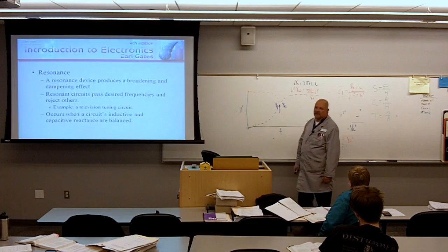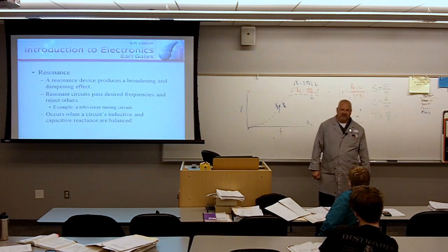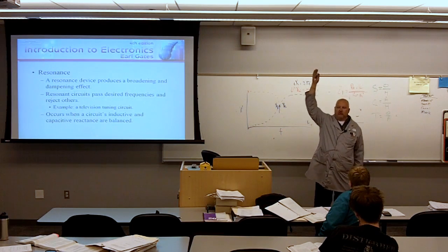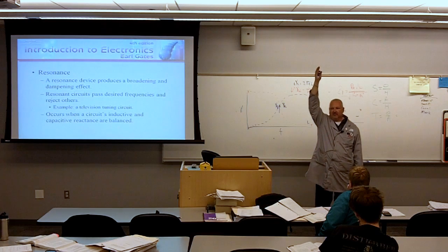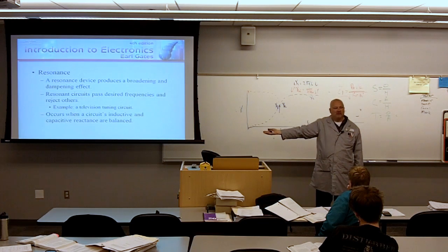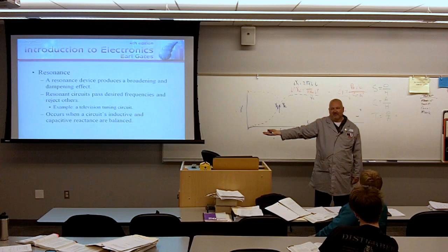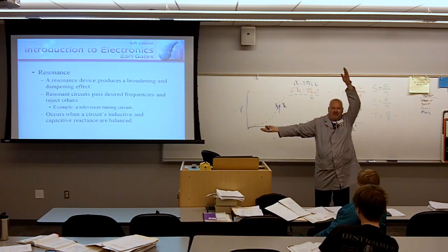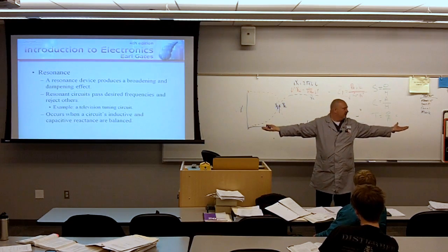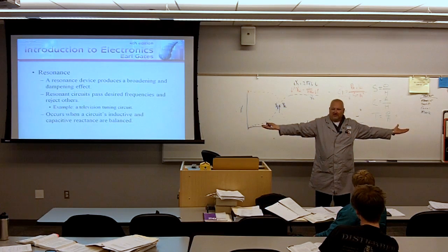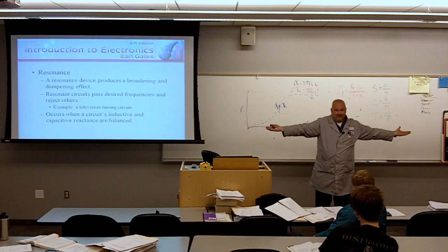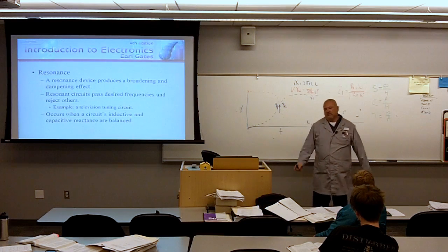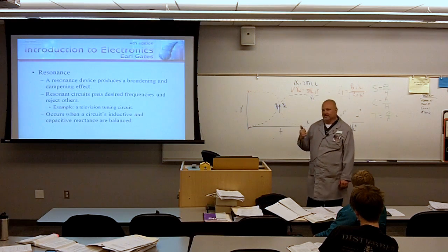How much phase shift does capacitive reactance give me? Pure capacitive reactance, how much does it give me? 90. How much does pure inductive reactance give me? 90, in the opposite direction. How many degrees of phase shift is there now between the capacitive reactance and the inductive reactance? 180. And they're both now at the exact same value, so what are they doing? Canceling each other out.